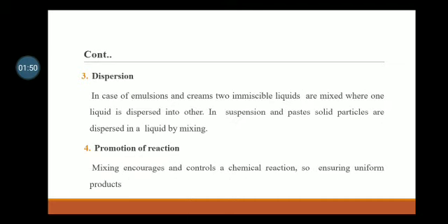The third, dispersion. In case of emulsions and creams, two immiscible liquids are mixed where one liquid is dispersed into the other. In suspension and paste, solid particles are dispersed in a liquid by mixing. Fourth, promotion of reaction. Mixing encourages and controls a chemical reaction, so ensuring uniform products.